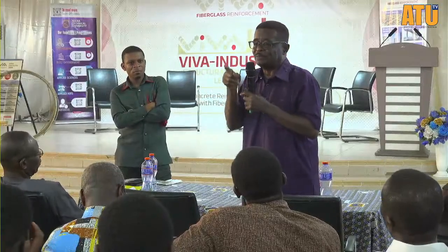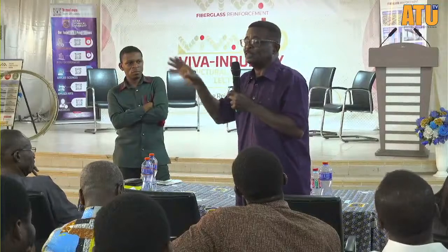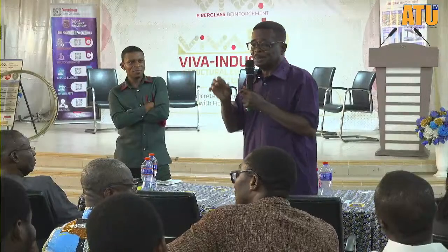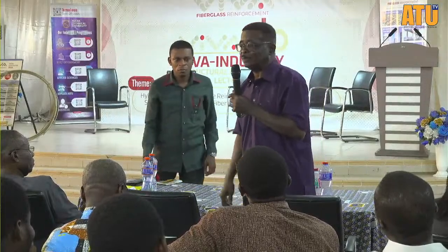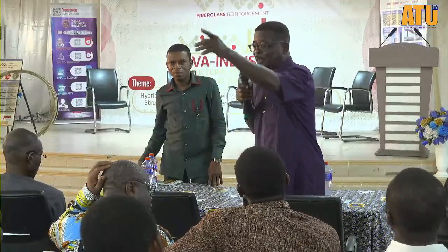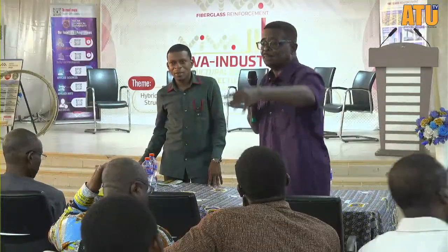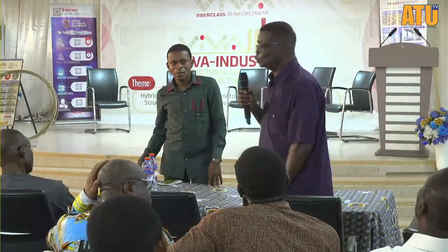And when you're talking about serviceability of GFRP, it's not about cracking per se, it's the deflection. The deflection in terms of serviceability is where mistakes can happen when you are doing that design. So durability, glass fiber, its durability is on the high side, not much problem. In a poor country like Ghana, the sensors are not there. So it's a very good thing for electrical engineering, electronics engineering. That collaboration is essential. Come out, study the various sensors and help the structural engineers.